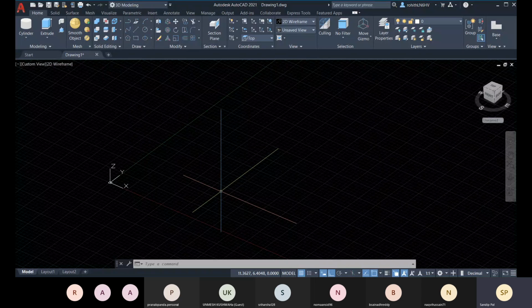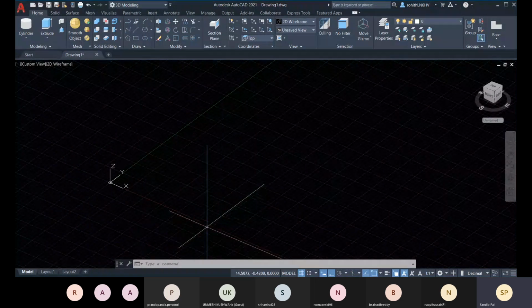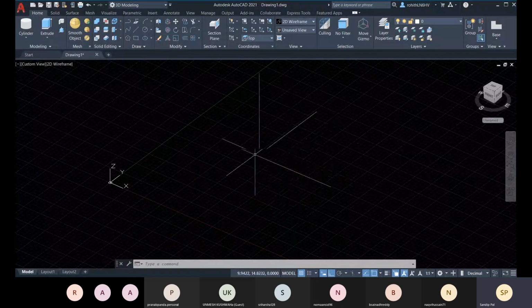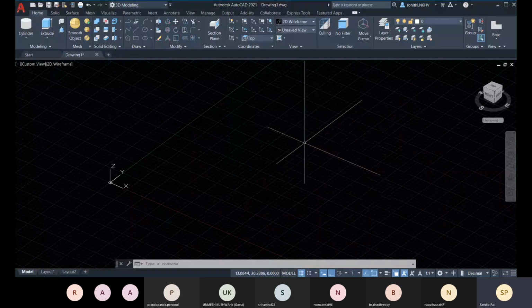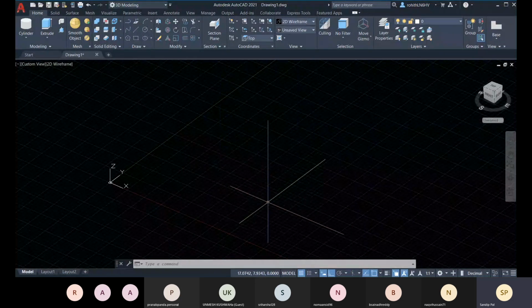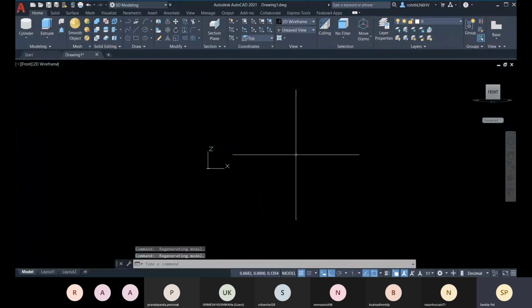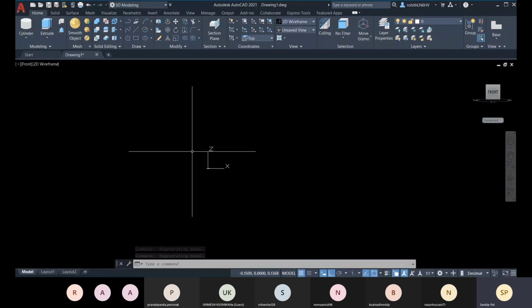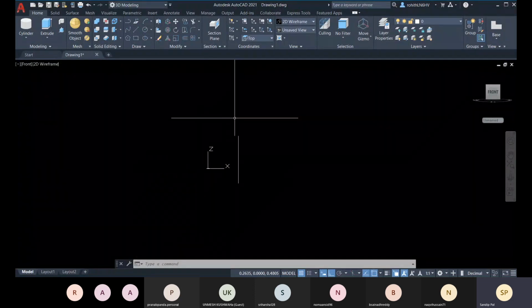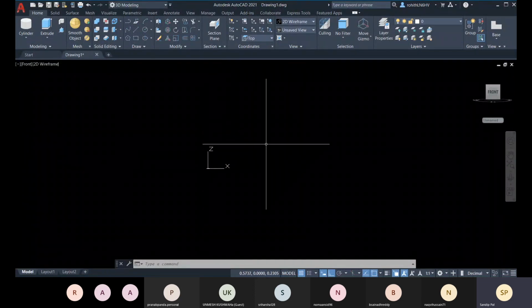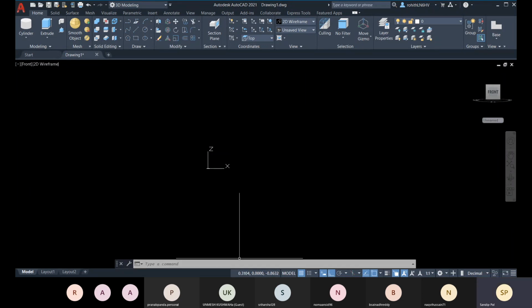At the beginning, I mentioned that the XY plane is the default working plane. Whatever you make will be created on the XY plane. So suppose you want to create a front view. As per the front view, right now this is XZ, and I cannot create anything in the XZ plane, right?